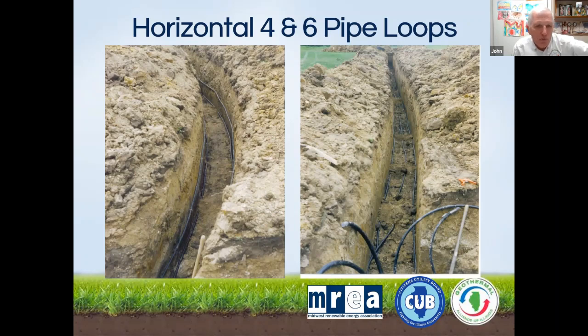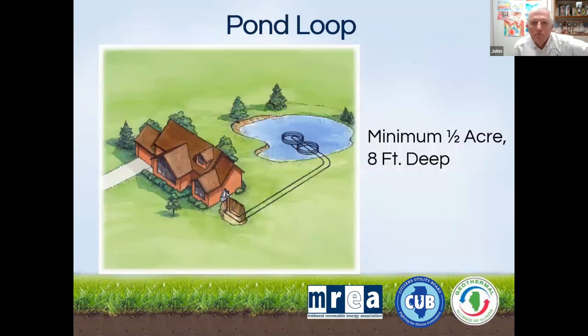You need a little more loop in this application, and you typically install those loops at depths of 6, 7, 8 feet in the ground. It's less expensive this way, but you do an incredible amount of tearing up of a yard. So you usually don't do this in a finished yard, and definitely not in a neighborhood, because you usually wouldn't have enough yard to handle this.